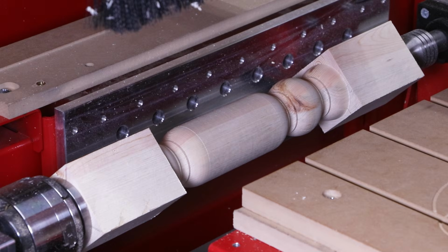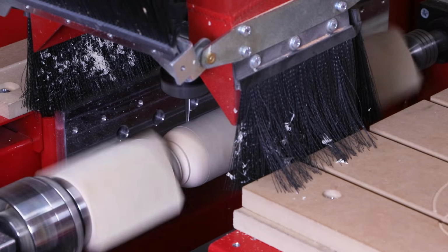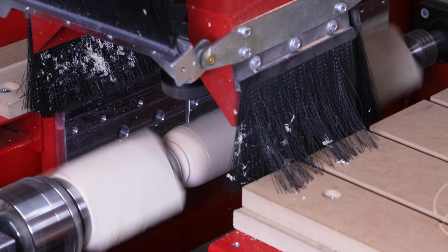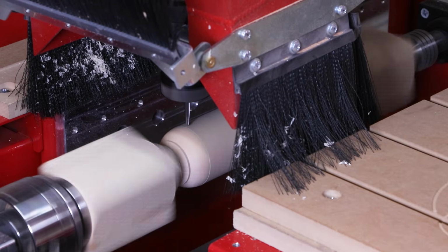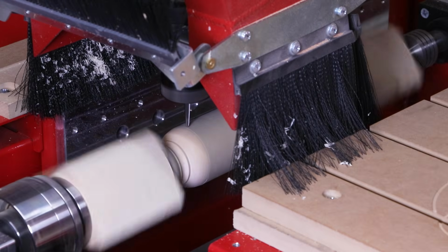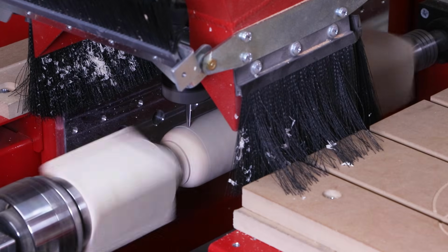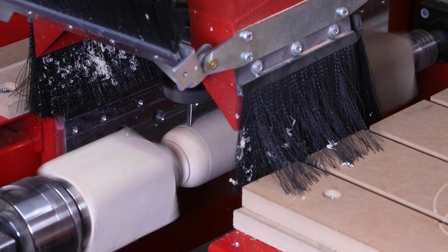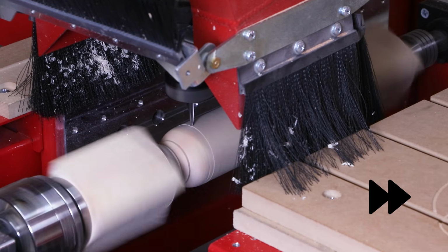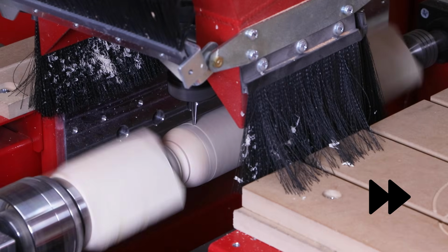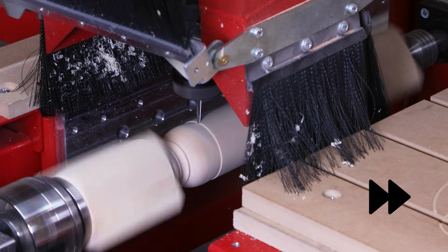The first thing that happens before the cutter even gets to the material is that it's going to continually rotate it at that 200 RPM speed. Now the cutter will approach the section diameter of 2.5 inches. It parks at about 1/8 of an inch above that section diameter and then slowly works its way into the material. So it might take a few seconds for it to actually make contact with the material when you're doing this the first time. The cutter is then going to slowly work its way down the material while constantly adjusting the Z-axis to give us that contour detail.